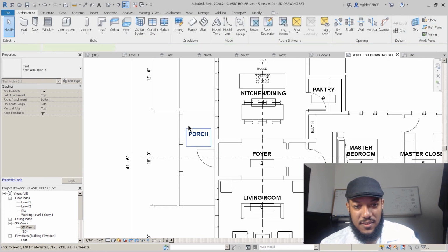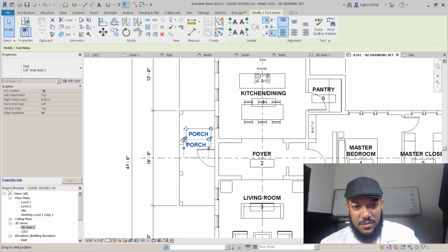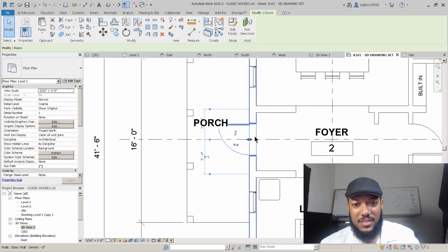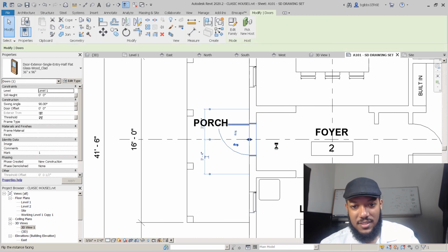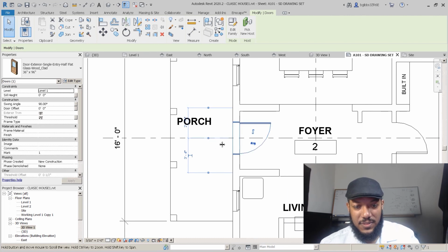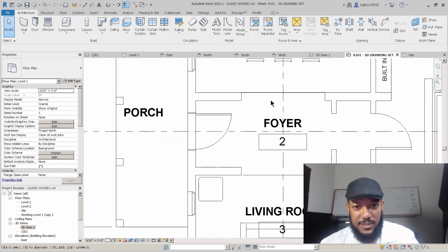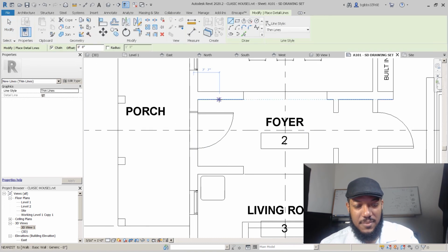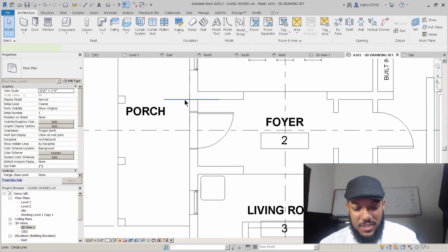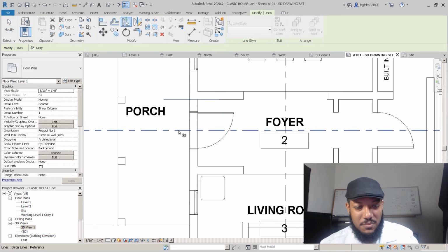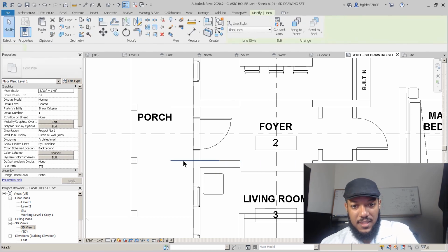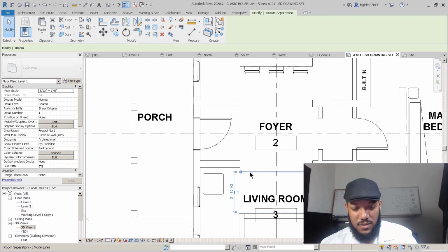And so you can see also, in addition to adding this, we're going to have our front door open inward because that's typical for residential. We just flip that direction. You see our lines are a little bit unbalanced here, so we want to come back actually and correct it before we're going out to print. We're mirroring this line. Press MM to mirror, and I'm going to align this with this inside wall, and probably move our room separator.